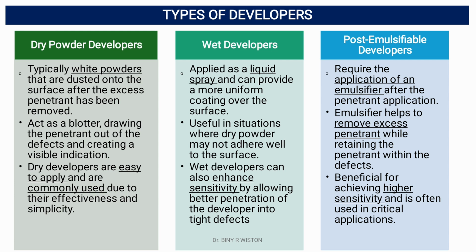Post-emulsifiable developers require the application of an emulsifier after the penetrant application. The emulsifier helps to remove excess penetrant while retaining the penetrant within the defect. This method is beneficial for achieving higher sensitivity and is often used in critical applications.